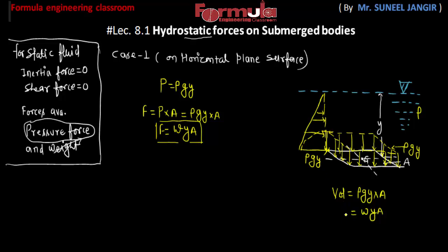Now, as we know this is the center of gravity of this plate, let me say the depth of the center of gravity of this plate from the free surface is yc. Obviously in this case, as the plate is in a horizontal position, y and yc will be equal.